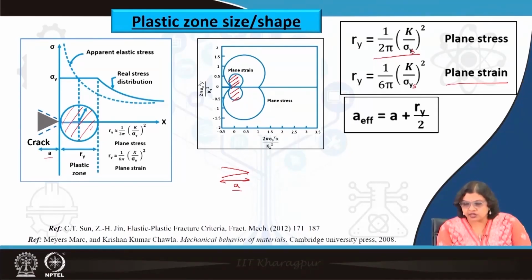We assume that once the crack grows, as I mentioned in the last lecture, the basic assumption of linear elastic fracture mechanics is that once the crack starts growing near the tip of the crack, it will lead to propagation and final fracture in no time. So, this propagation is unstable, the growth of the crack is unstable, right,